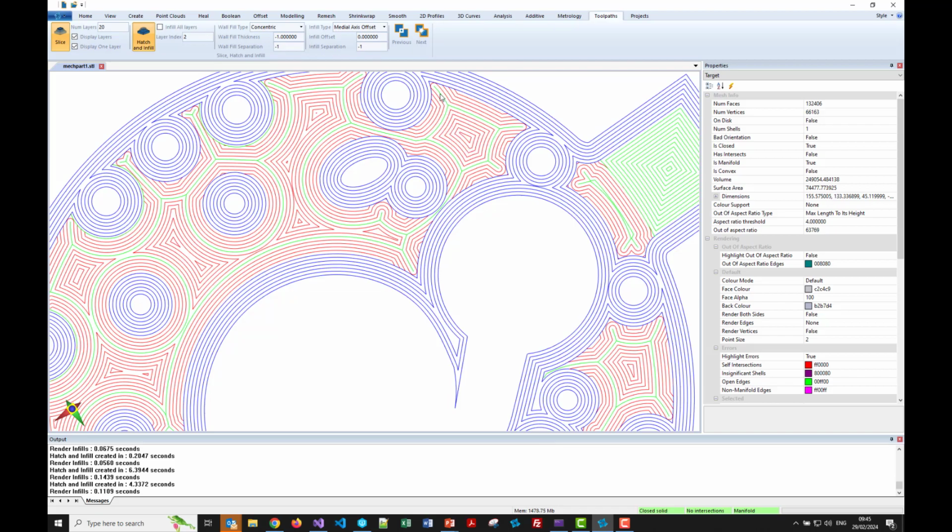But then the medial axis is available to go into corners and to cross bridges. So the idea here is you're mixing two different patterns. One is this fairly standard offsetting pattern, and the other is the medial axis to make sure you don't miss material in extreme parts of the geometry.